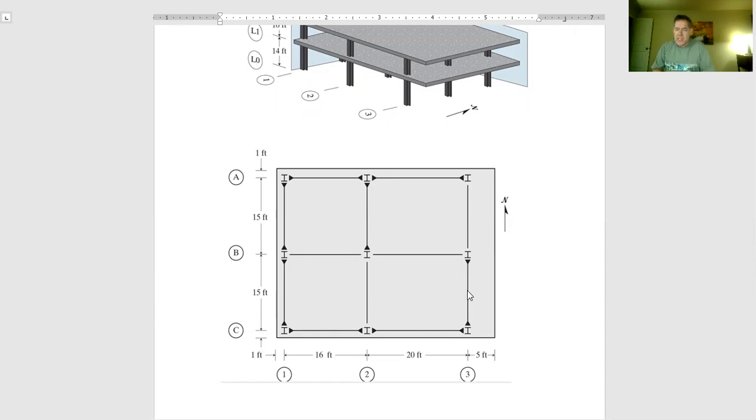means that those are shear axial only connections. So when we draw our model, we're going to have, of course, two stories. We'll have pins for the supports, because that's what we were told was happening at A, B, and C. And then we have two stories, and we have a moment frame over on the left side, meaning the BC side, and from A to B, we would just have hinges on each end of the beam. Do not put the hinges in the column. We don't like hinges in columns. That tends to create some instability concerns. So the column would be continuous over those two stories, is what that means.